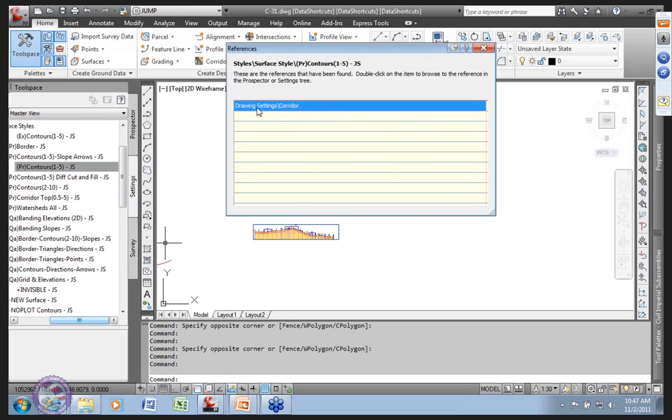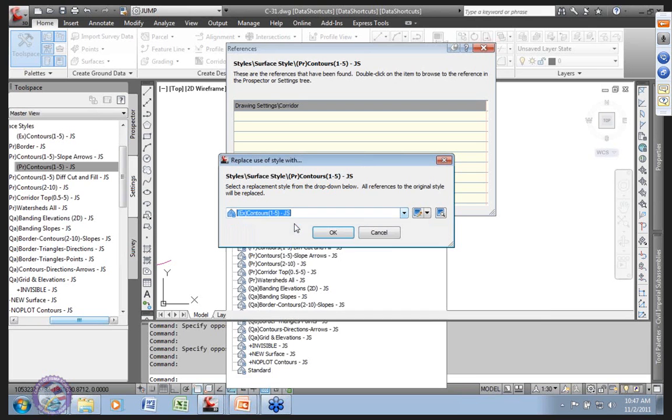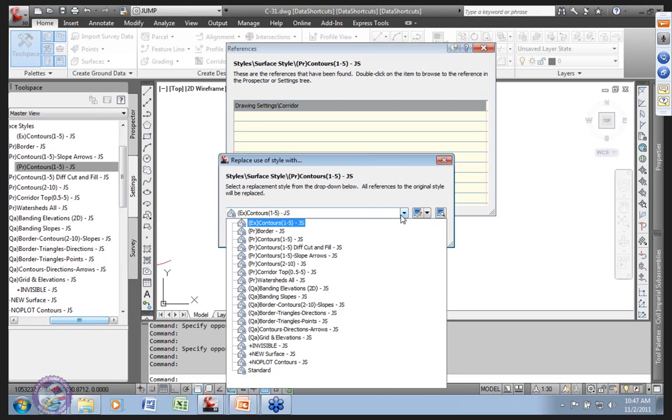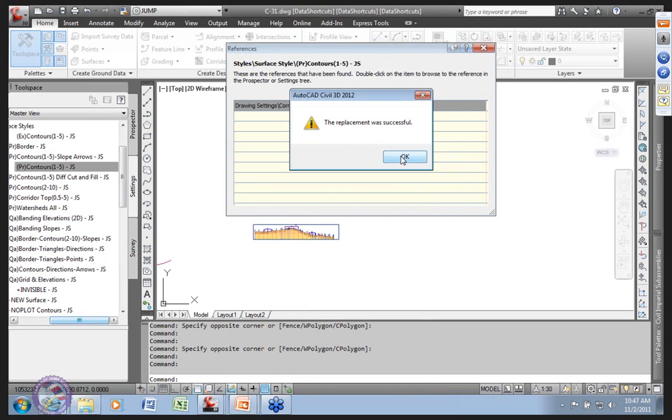That's one of the more useful things in Civil 3D: just like our label styles, we can have drawing settings, and I would like to replace it. Instead of 1 to 5s by default, I would like it to do existing every time I build a corridor. Or maybe I want one that does 1/2-foot contours and 5s, which makes it easier because most of the time the roadway is pretty flat. So we can replace that.